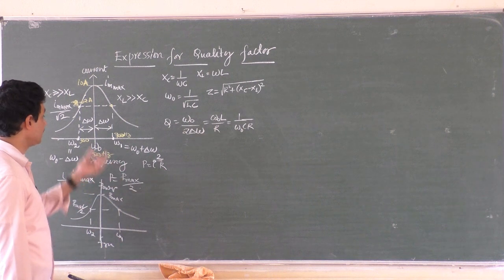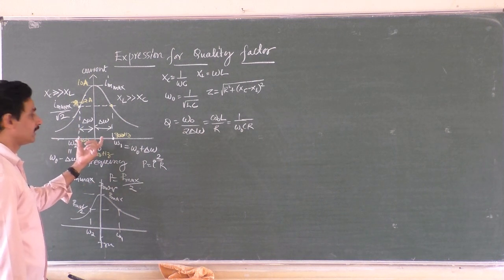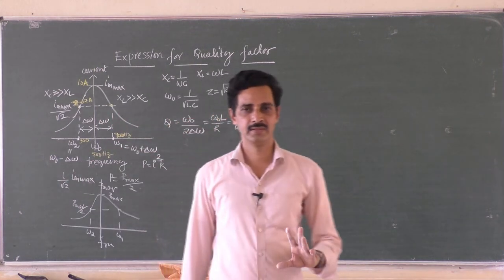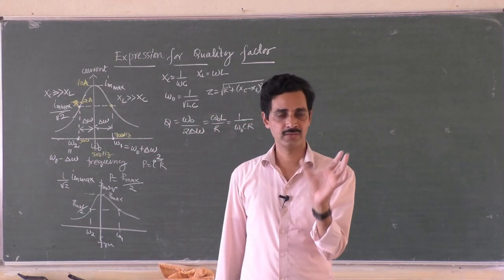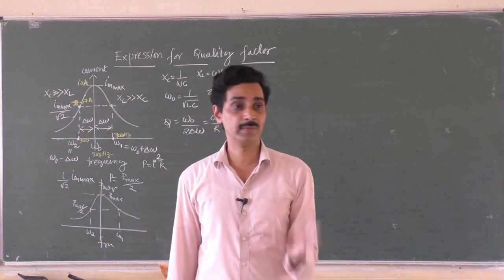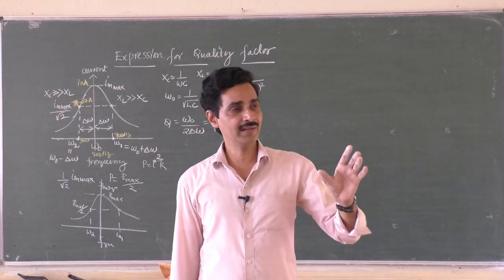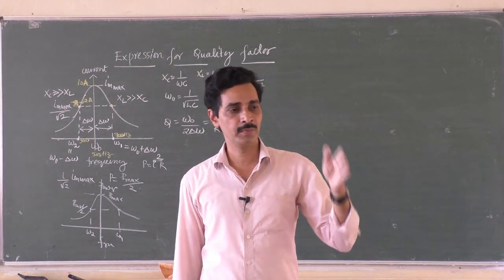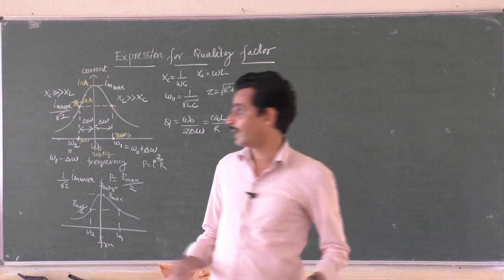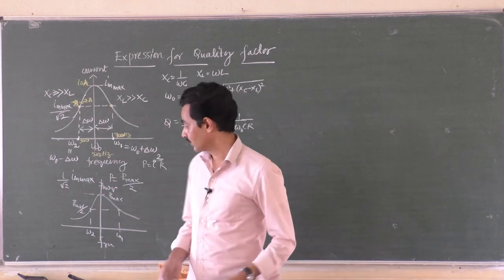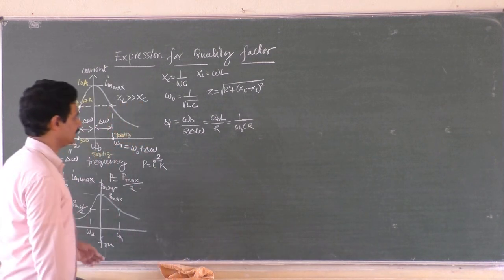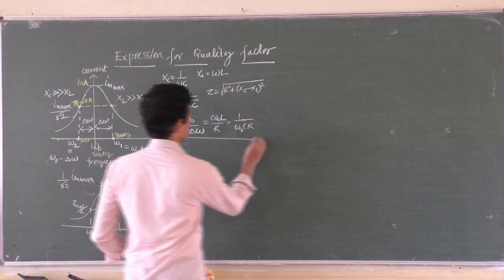So resonant frequency, what is bandwidth? The difference between the higher and lower cutoff frequencies is called bandwidth. So every TV station or TV channel will be given a bandwidth. So you can communicate your signals from so many megahertz to so many megahertz. That is its bandwidth, and it works between those two. Whereas for radio communication, one frequency is enough. It is very sharp. So quality factor or sharpness of resonance.